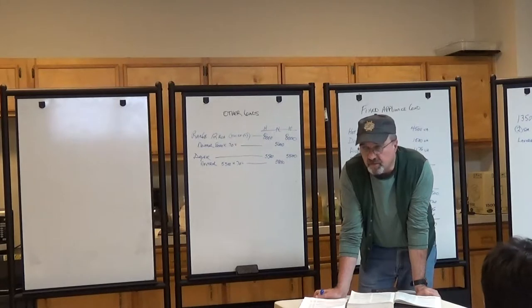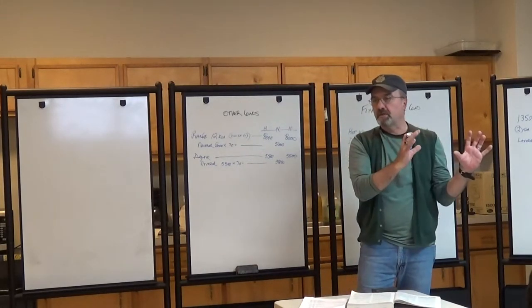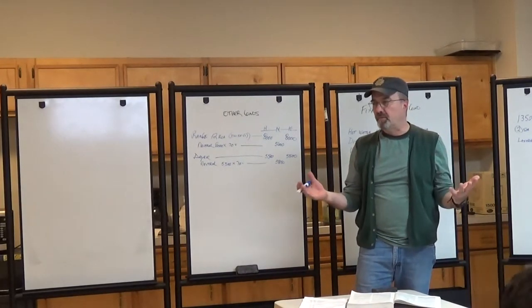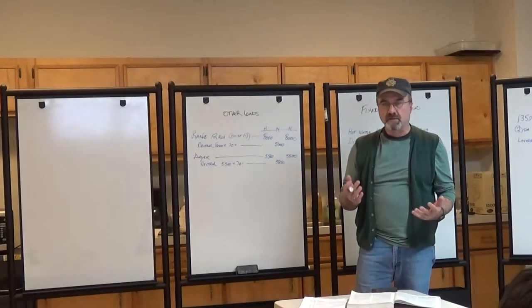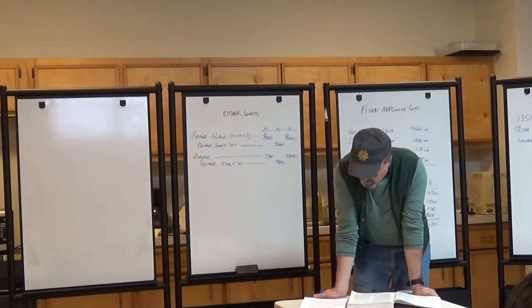Okay, so the code recognizes that, for sizing the service entrance conductors, we are not going to have the air conditioner and the heater running at the same time, okay? So what the code is saying is that whichever is larger is what we have to size for. Okay.